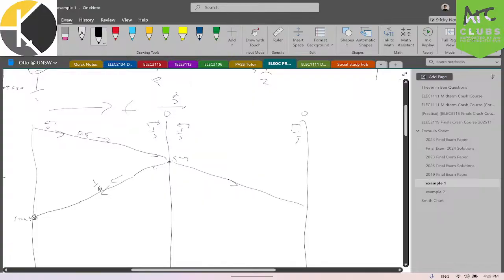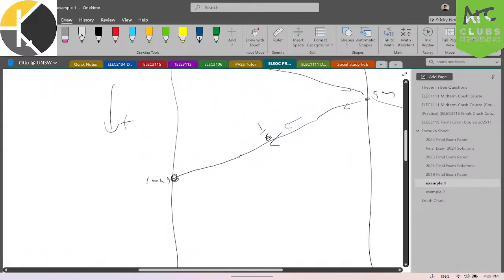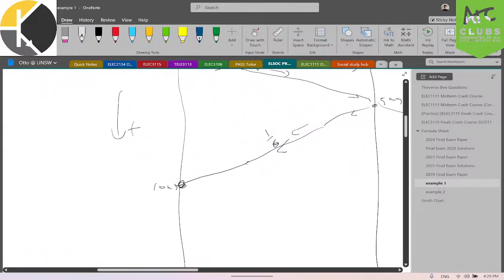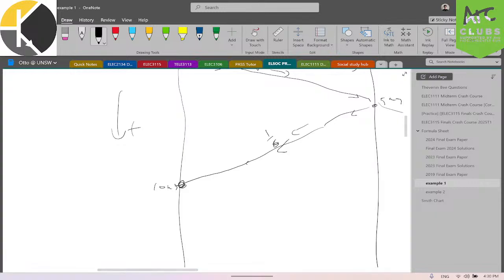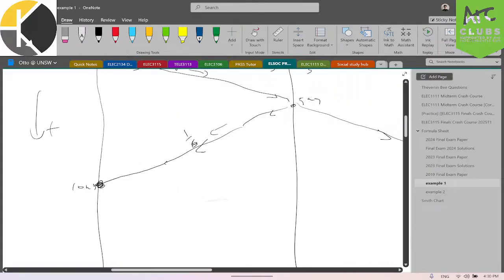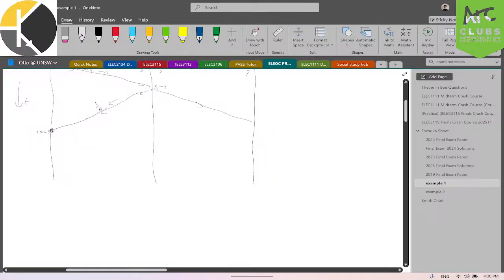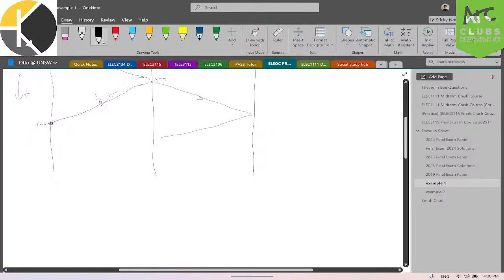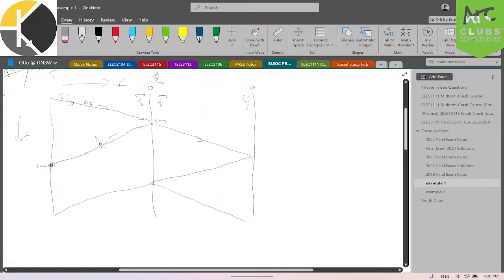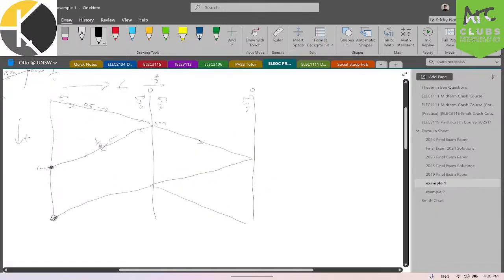The cables are of equal lengths, and you can see that the wave reaches back to the start. It is going to terminate because the source impedance is the same as the line impedance. It's going to be perfect termination. So this wave just sinks into the source. It doesn't get reflected again. But this wave will reflect again back and then reflect back and transmit like this. So those waves always terminate at the end, but those waves always will go back and forth with a factor of 1/3.